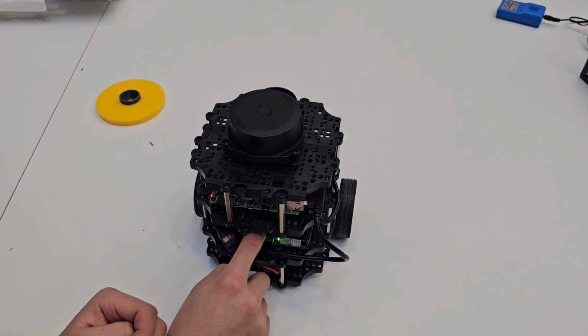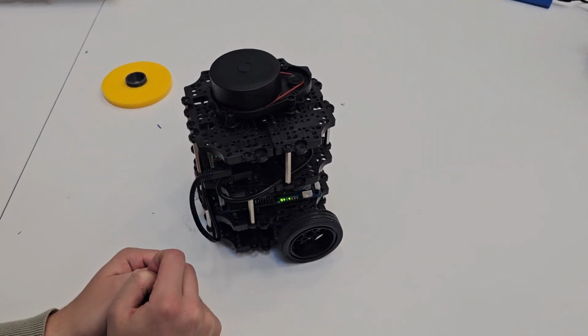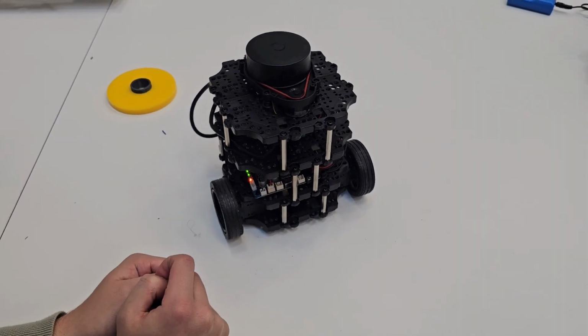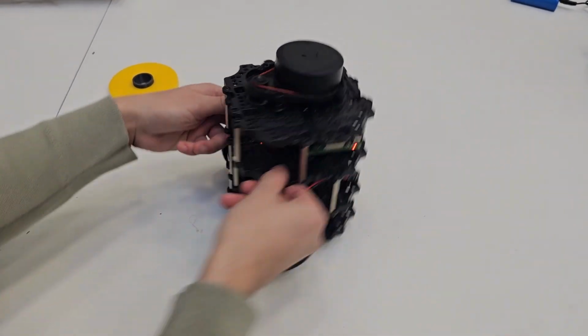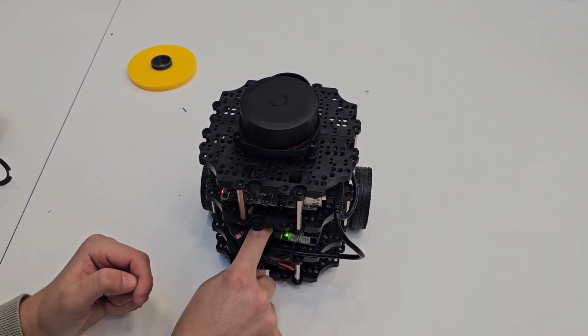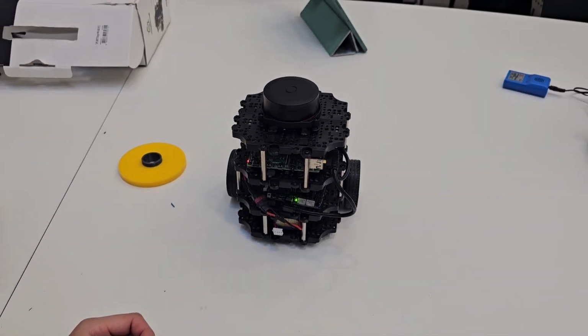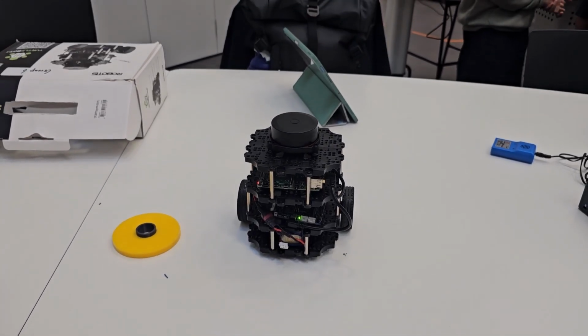We began by assembling the Turtlebot 3 Burger's hardware. Before configuring the network, we validated our build using the standalone mode. By triggering the OpenCR board's built-in test sequence, we confirmed that the motors and sensors were fully operational independent of the remote computer. We pressed a button that made the robot do a 180 degrees turn and another that made it move 30 centimeters in a straight line.